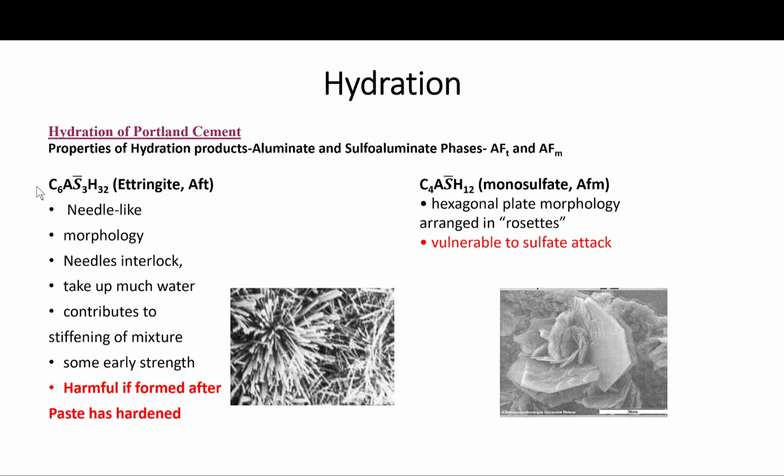This is also referred to as ettringite, as I mentioned, which forms needle-shaped prismatic crystals, as can be seen here in this micrograph under the SEM microscope.